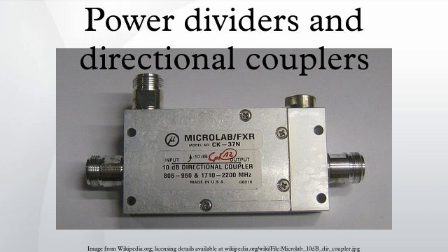A single λ/4 coupled section is good for bandwidths of less than an octave. To achieve greater bandwidths, multiple λ/4 coupling sections are used. The design of such couplers proceeds in much the same way as the design of distributed element filters. The sections of the coupler are treated as being sections of a filter, and by adjusting the coupling factor of each section, the coupled port can be made to have any of the classic filter responses, such as maximally flat, equal ripple, or a specified ripple response.